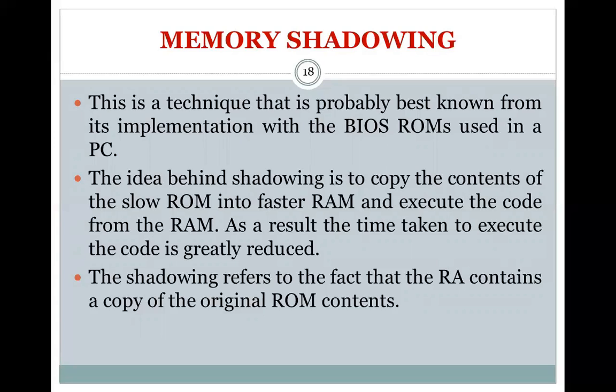The mechanism can be implemented either with hardware assist or entirely in software. The basic principle behind the hardware assisted implementation is that the address decode logic is used to switch the address decode to select the RAM instead of ROM. The second technique is the software based implementation, in which the software that is copied is now in a different memory location, provided the software was compiled and linked to execute in this location. So using these two mechanisms, we can eliminate the memory shadowing problem.